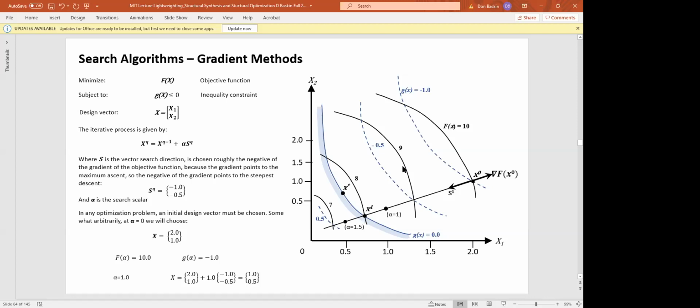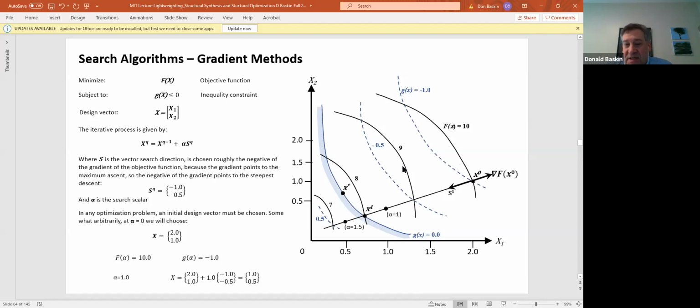Exactly. Okay, so that method is called topology optimization, and we're going to go into topology optimization in great detail. I've used topology optimization to great success on body structures and some suspension components and some transmission housings. The software, or the concept, originally was developed without what you're calling these manufacturing constraints. As these tools have become more popular in industrial applications, the people who write these software packages have very much focused on design constraints.